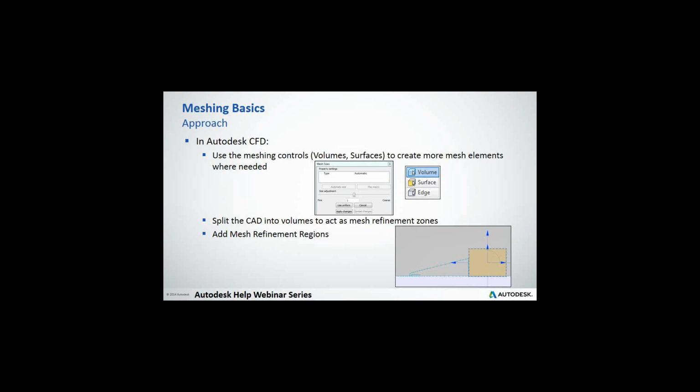But the problem I was facing in CFD was that the elements were so coarse because it was this huge open garage that didn't have any CAD below. Again, it's based off of edge lengths and distance to other geometries, so sometimes it can get a little too coarse. So I love CADing that stuff, and refinement regions are awesome too. So yeah, this is a good point.